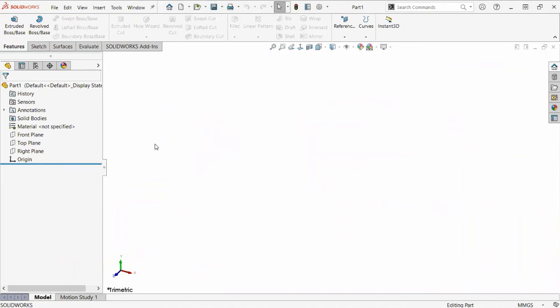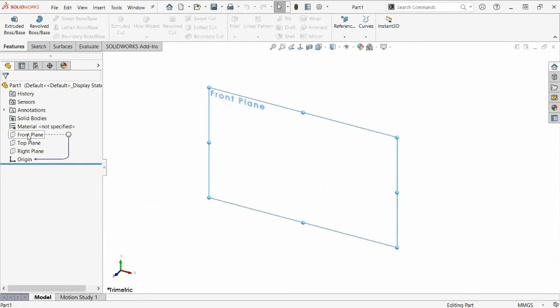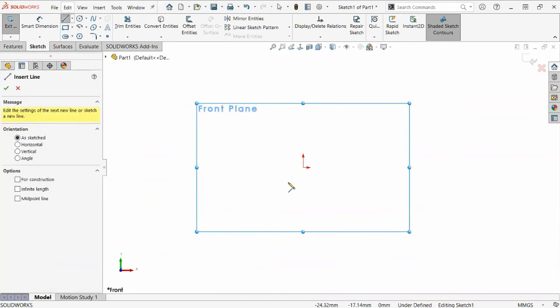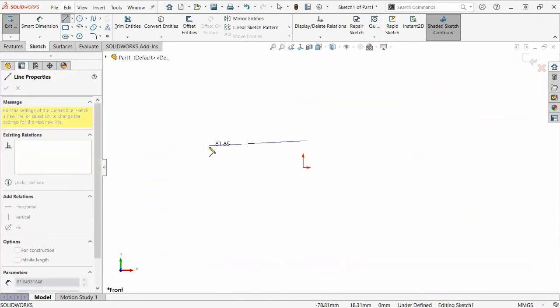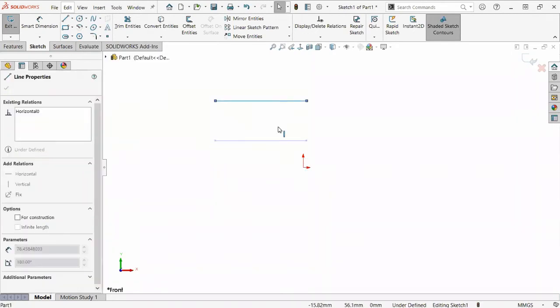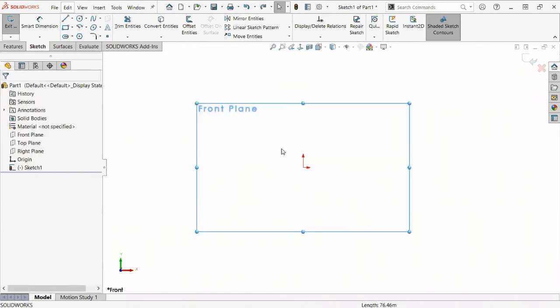And you have to create your initial sketch on an existing plane. So I think for this one, I'm going to use my front plane, and I can right click or left click on the front plane and choose the sketch icon to quickly make a sketch. And it's always good to start your part from the origin, one of the things we discussed. So if I click a line out here and start randomly, there's nowhere for that first point to be anchored to. So SOLIDWORKS won't have a starting point to make sure all this geometry won't move around on you by accident. So I'm just going to undo to get rid of that and go back into the line command.